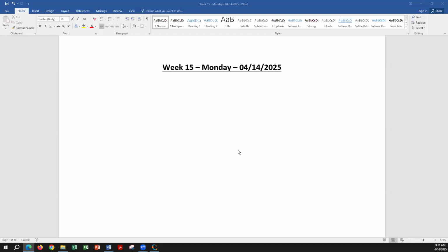Yeah, so this is the response of an ideal bandpass filter. You have a stop band on each side and the pass band. Ideally, it goes from the stop to the pass band at the same frequency, which is not possible in the real world because the components, as we know, capacitor and inductor, require some time to energize and de-energize. So you always have a transition band going from the stop band to the pass band.